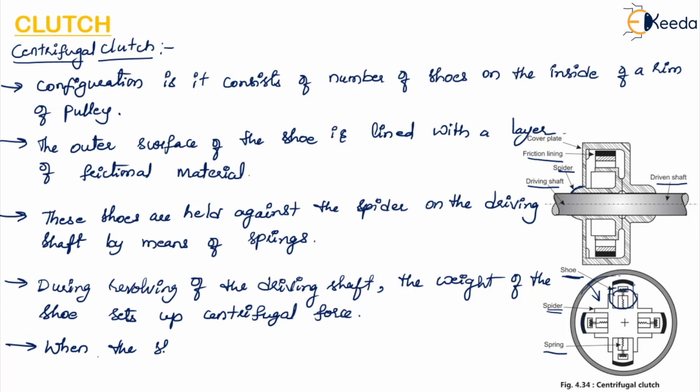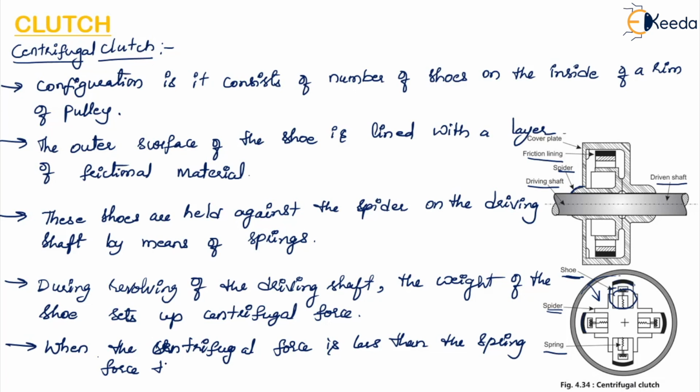Here there are two forces acting: the centrifugal force and the spring force. When the centrifugal force is less than the spring force, the clutch is not engaged. When it is not engaged, the driven shaft will not get any torque.